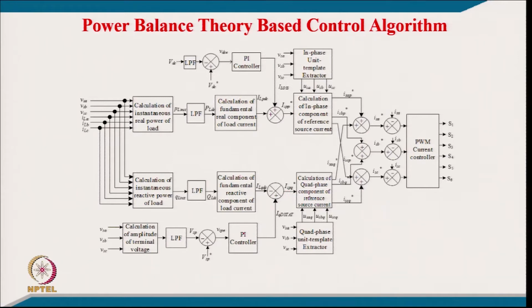So, the DSTATCOM will supply this locally to the load, and the remaining difference of these two has to flow into the supply for regulating the voltage at the point of coupling, because some leading current has to flow into the supply feeder impedance also, otherwise you will not get zero voltage regulation.